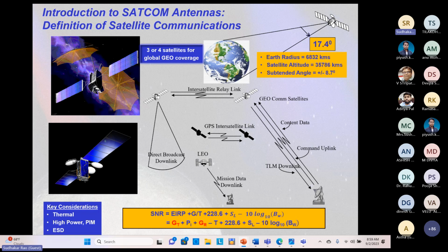That means you don't want to increase the power per channel too much, because then the satellite cannot handle it. So that's limited, and the gain is a key factor. All the pressure is on the antenna engineer to maximize the gain, on both the transmit and receive antennas. Even 0.2 dB of gain makes a big difference. It's either you win a proposal or lose a proposal. That's why you need to really optimize the gain. That means you have to maximize the directivity and minimize the losses. So you have to find a way.